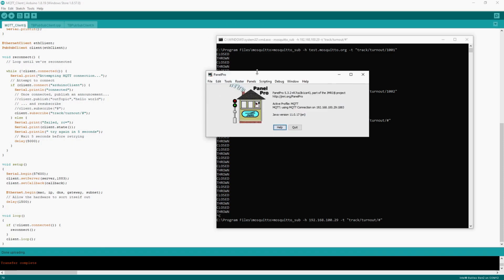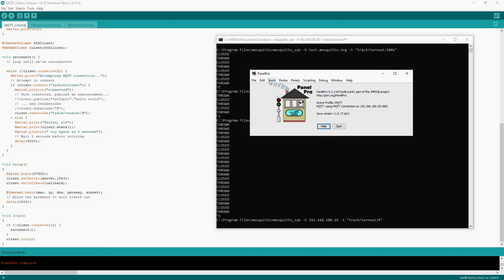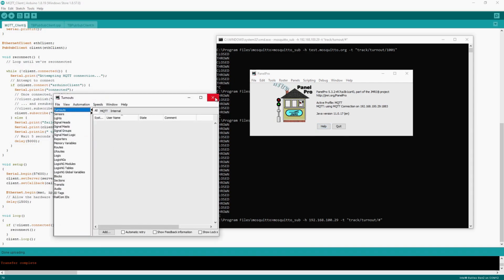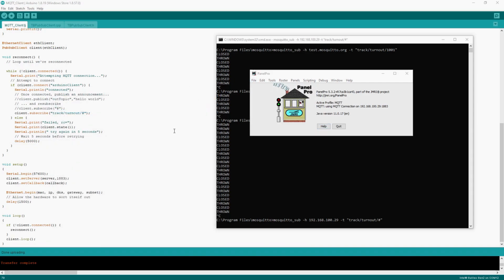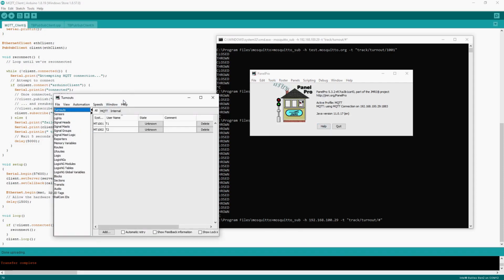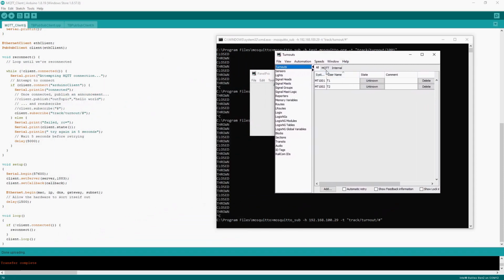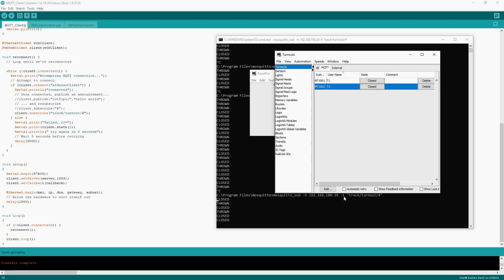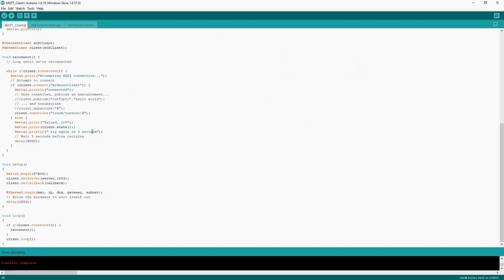It's probably, well, there are no topics on this server yet, so there's nothing for it to remember, but I'm hoping I'm connected, so it's not going to have any turnouts because I haven't opened the saved settings file. Let's open the settings file. We now have some turnouts, and I would hope that when these turnouts get moved now on MQTT, even though they're in the same profile, we're now publishing to a different server, which is hopefully the local one. So yeah, this is promising. We're getting a response now on this IP address. So it's time now to try and consume this in an Arduino sketch.